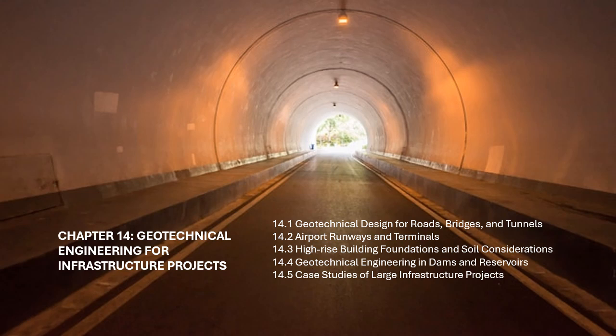The terminal building's foundation design must accommodate heavy aircraft loads, structural weight, and the dynamic forces resulting from daily operations. A thorough subsurface investigation, which may include boreholes, geophysical surveys, and laboratory tests, helps determine the soil shear strength, settlement characteristics, and groundwater conditions.